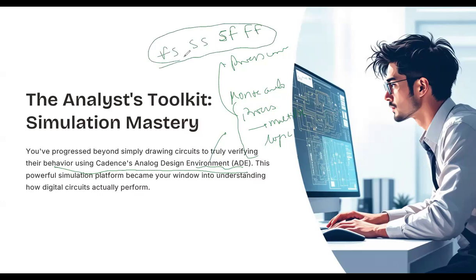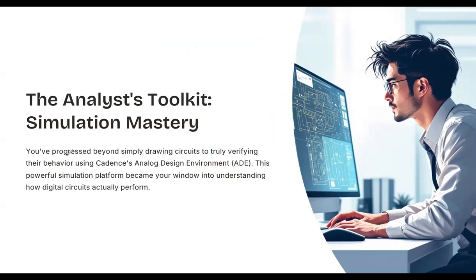These all four process corners are in ADE L only. This process corner simulation is done in ADE L, and Monte Carlo simulation is done in ADE XL. So these are two different things when we work with ADE. And most of the operations that you can do using ADE, when you start working on it, you will keep on learning that we can do a lot more things than we have done so far.